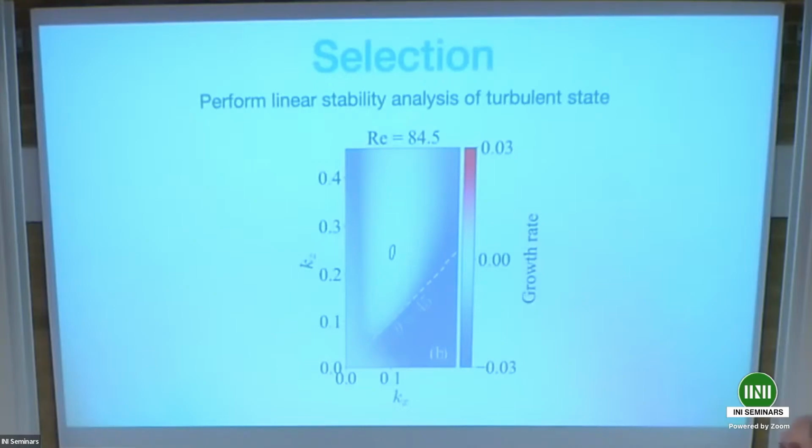Well, okay, so first, what is the case is that if you look at all the results published for channels, there's less on Taylor-Couette than you might think, plain-Couette, et cetera. The angles are all over here, less than 45 degrees. I'm not saying that you never see something. In fact, when you go to low Reynolds numbers, they do begin to approach 45, but they seem to hit a hard wall, which you can even see in this linear stability, that there's something at 45.